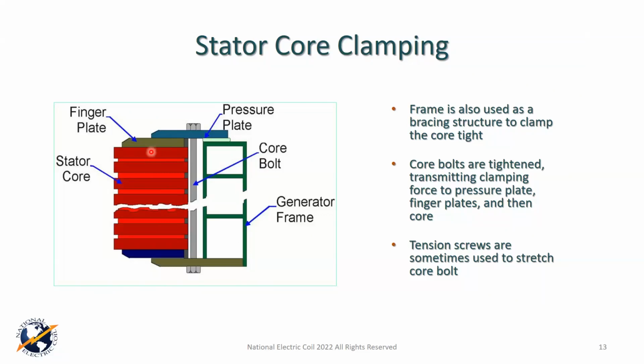Now, on repairs, we do an awful lot of repairs horizontally, but it's typically not a full restack, because when you get much past half of the length of the core and you have it laying on its side, all those laminations that you had nice and tightly aligned, if you don't keep them tight, it starts becoming like a house of cards.